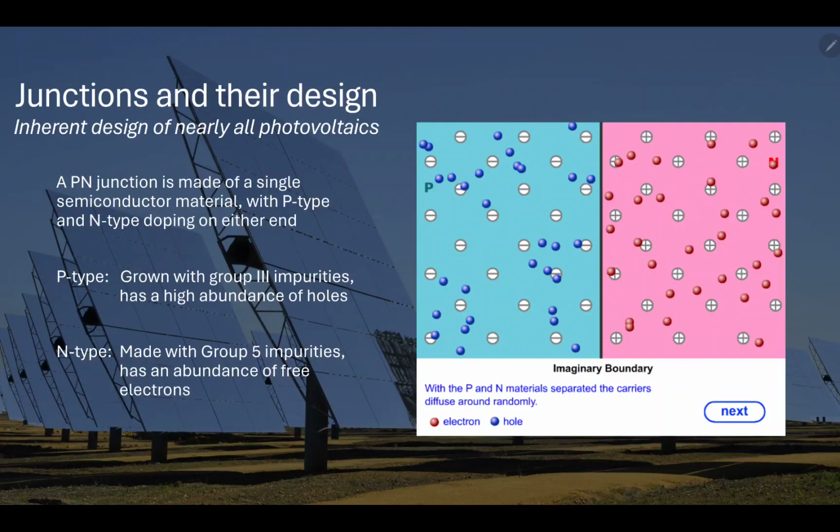Like mentioned before, since group 3 only has 3 valence electrons, when you put it in a group 4 semiconductor, it can only fulfill 3 of 4 bonds, creating an abundance of holes. The n-type is made of group 5 substitutional defects, and since they come with 5 valence electrons, that extra one becomes a free electron that can fly around the material.